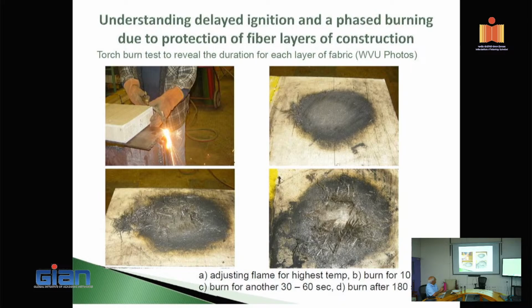So this is a sandwich composite, and that's a 1/4 inch sandwich. That's a balsa wood, and we have about 24. We talk about it in Fahrenheit. That's about 11, 12, 1300. So my message to you is, this has about 40, 45 layers to make a 1/4 inch. I was asking somebody yesterday, they were using 45 layers. So that 1/4 inch has 45 layers of 24 ounce per square yard composite.